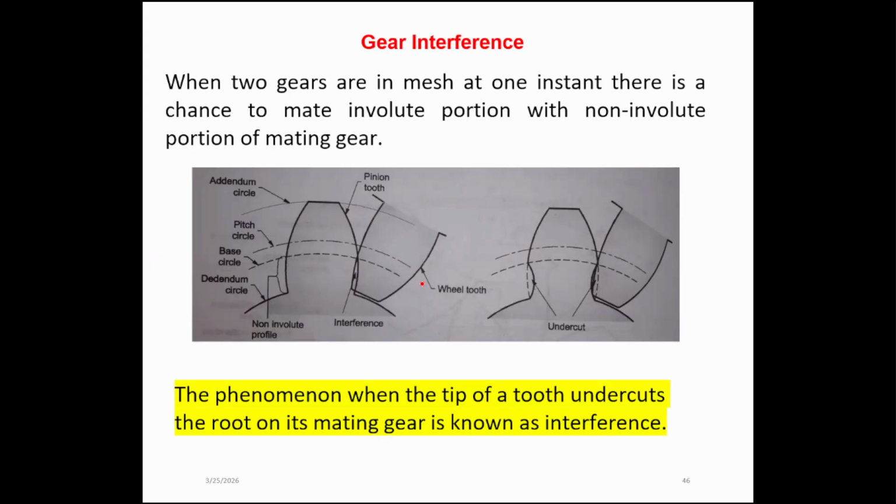The only thing is that gear interference should be avoided with proper manufacturing methods or proper center distance placements, right? So this is the interference happening there. This basically generates huge noise, huge wear, and also some lowered power transmission. If the gears are locked together, it will generate additional resistance to rotate, right? So it will be a kind of loss in terms of power transmission, right?